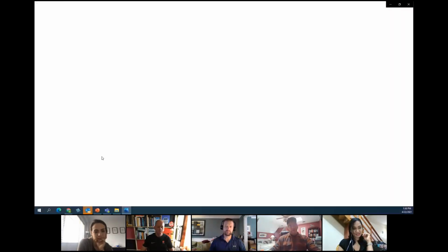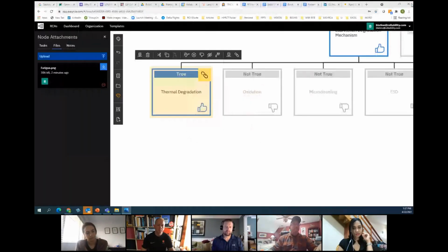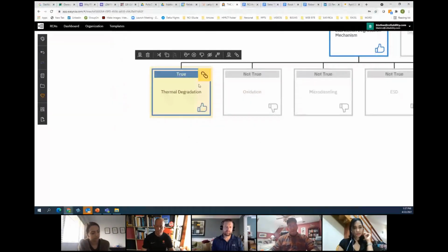After reading the fractured surfaces, you're going to be able to put the pictures on there that show how a metallurgist would read it. And this being, you see the traditional beach marks of a fatigue type failure. So whether it's a metallurgical report, an interview, or an OEM policy, you can attach anything you want in here, but it has to be able to serve as evidence to prove or disprove the hypothesis. And ideally, every block on here should have a paperclip.